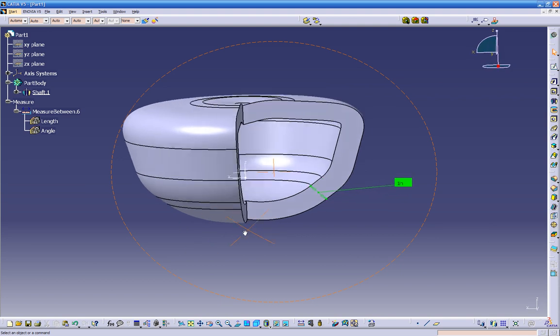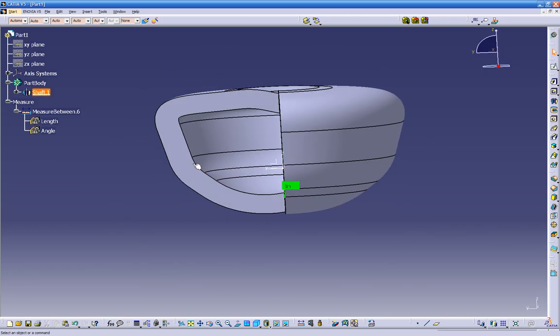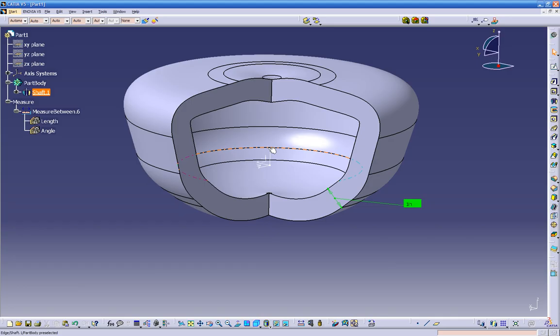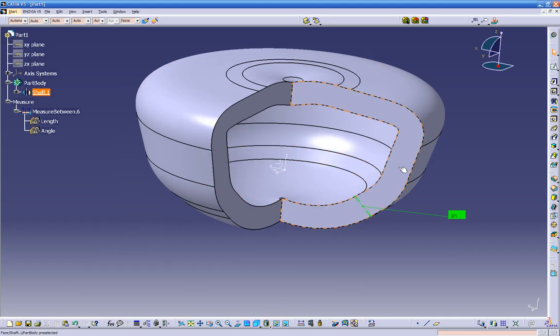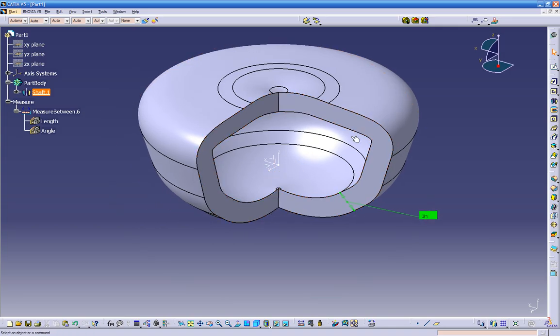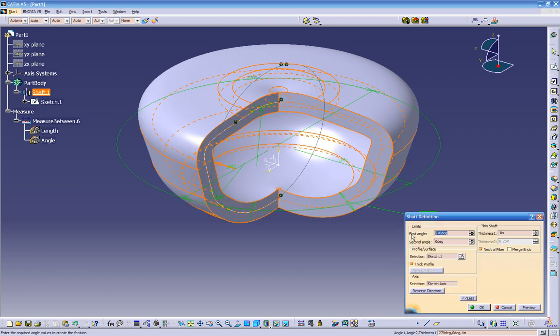let's try to build now a sketch on this surface over here, or we can build it on the plane, because right now, as you see, our plane is in the center. So it can go either on the XY, on XZ plane, we can create a sketch right now, or we can create a sketch on this plane. We can do either or. Let's go a little bit more advanced this time. So instead of going on the regular, let's change its angle to, let's go odd number, 223.